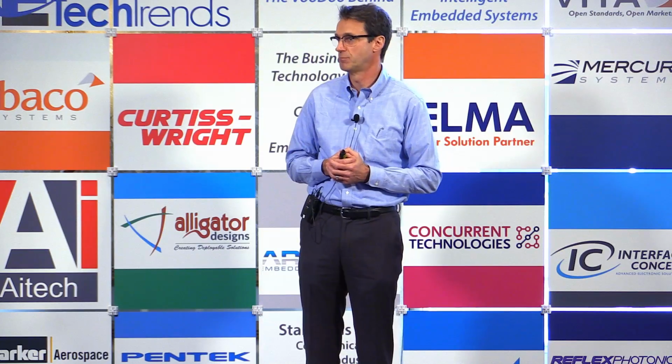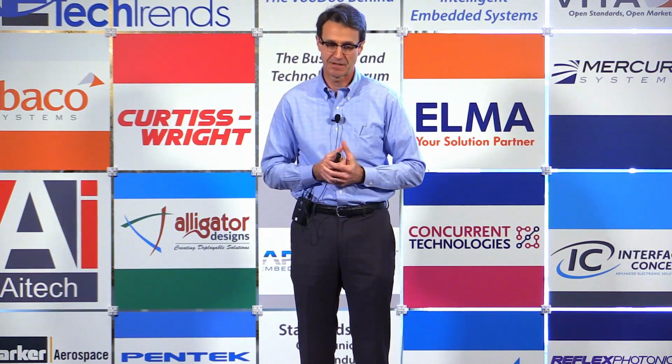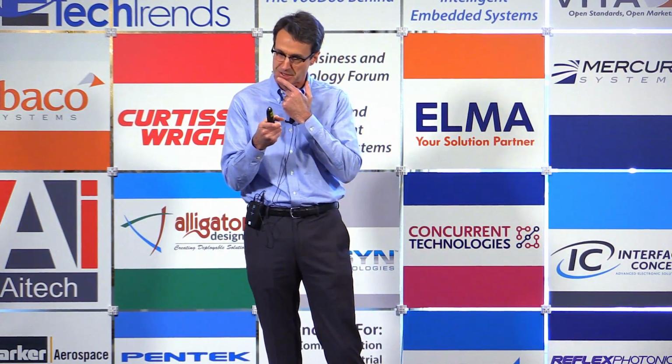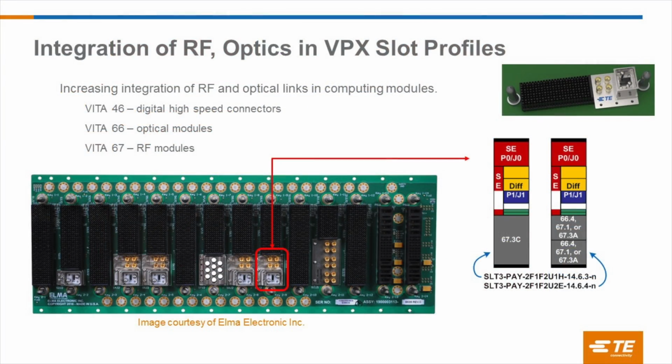You can also see there's a module there with open cavities, 10 cavities. That is part of what we've been doing on VITA 67.3. So we've been working on modules that are wider, that'll support a 1-inch pitch instead of a 0.8-inch pitch, which really is a large percent of the applications. And that allows us to get 10 coax contacts within a full module space. So a little bit of an increase in density and some new capabilities there by stretching out the size of the module. But what I wanted to focus on for this was the module that's shown there with the RF and the optics in it.